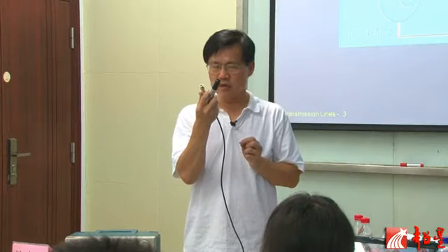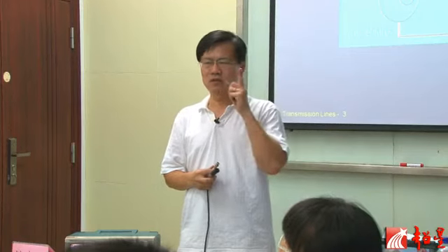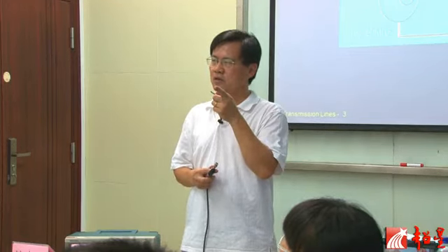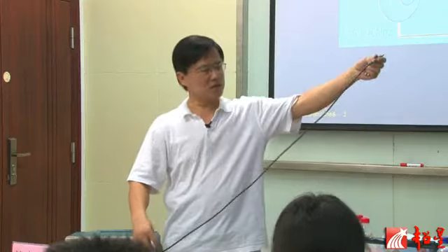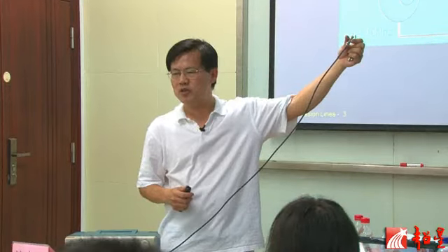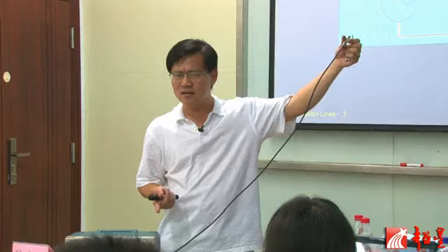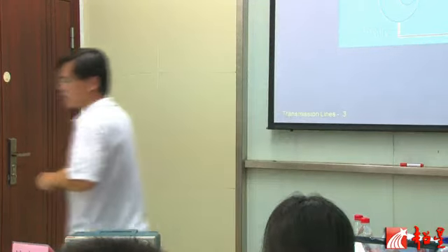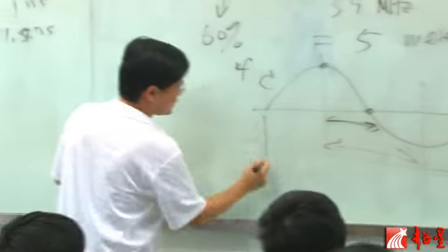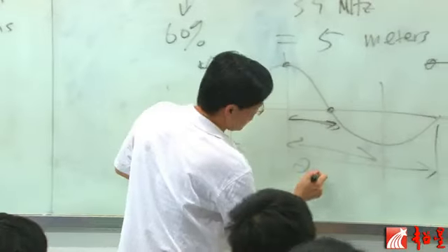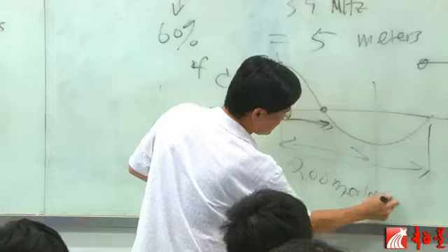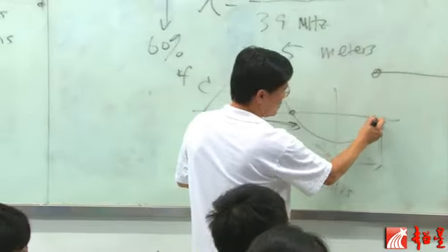Now this is really a short circuit, right? Okay, what's the wavelength of a 1 megahertz wave? It's 200 meters, right? What is this compared to 200 meters? It's almost 0, right? Okay, so basically, if you think about it from the wave propagation point of view, this is your wavelength. It's 200 meters, right? Then I'm looking at a 1 meter cable.